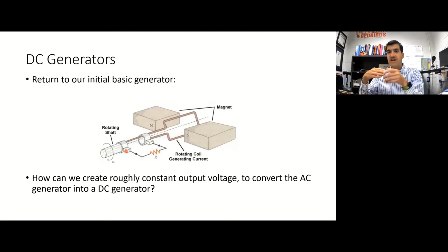And they just ride on that slip ring as it's rotating around. And then same thing for this side of the armature. We have this side connected to this slip ring, so it's rotating around with this side of the armature, and riding on it is this brush. And then the brushes are connected to wires, which connect to the electrical grid, which in this case is just represented by this resistor right here.